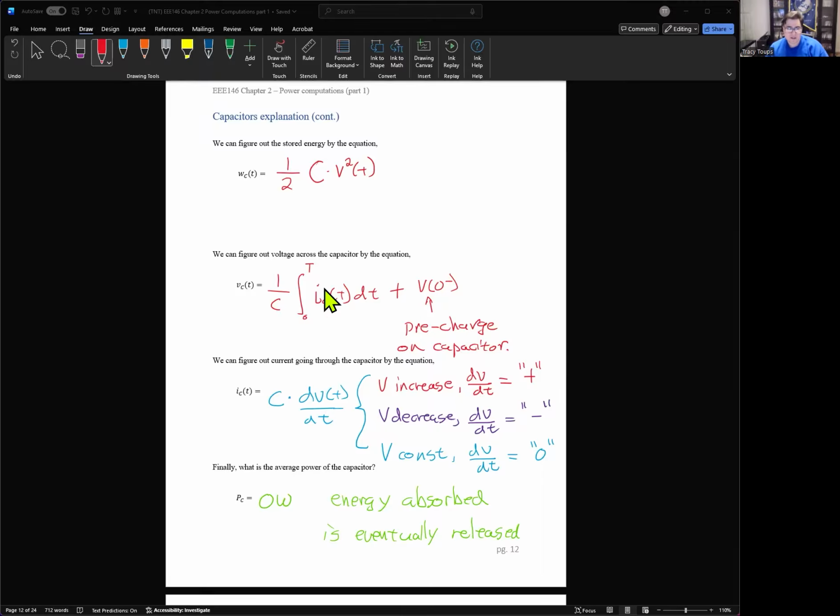In terms of current, there's only one way to fill up the capacitor. You got to start dumping current into the capacitor. Okay, the higher the current, the bigger the amps, the faster it's going to fill up. That's obvious. If you put 1 amp versus 50 amps, it's going to fill it up 50 times faster, right? The other thing is time. If we take 5 minutes to fill up a capacitor versus 5 seconds, obviously, given the current is constant, 5 minutes means we're going to have a lot more energy stored, right? We're going to have a lot higher voltage. So the amount of time you put the current into the capacitor is going to raise its voltage. You have to calculate how long you're doing it.